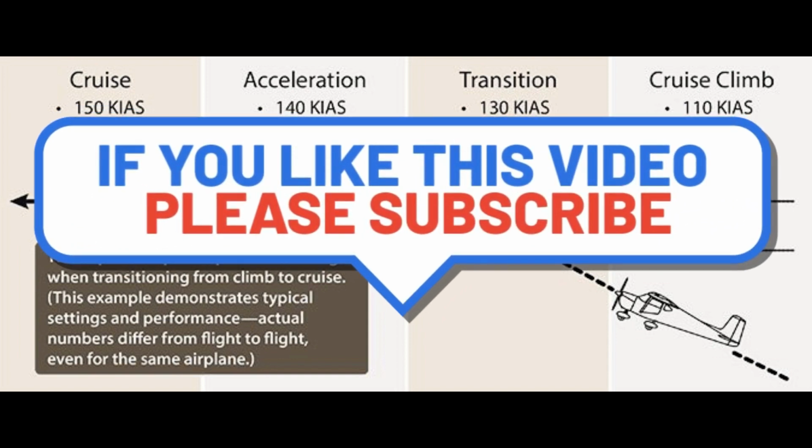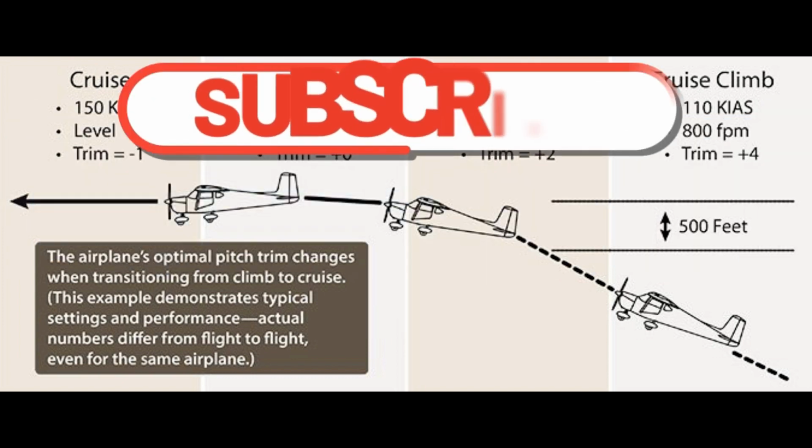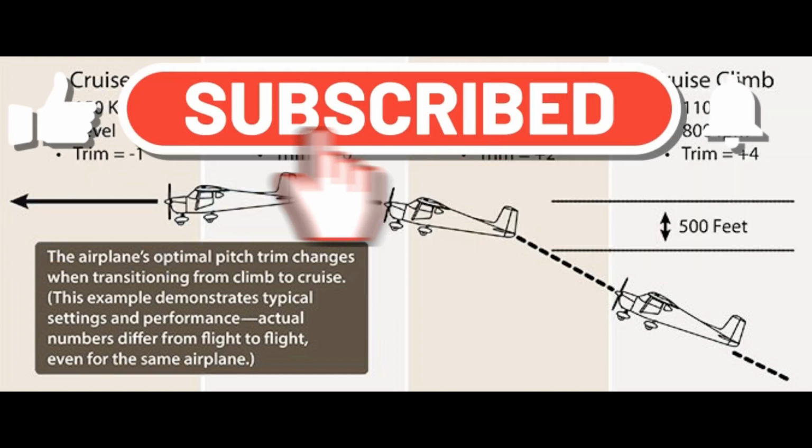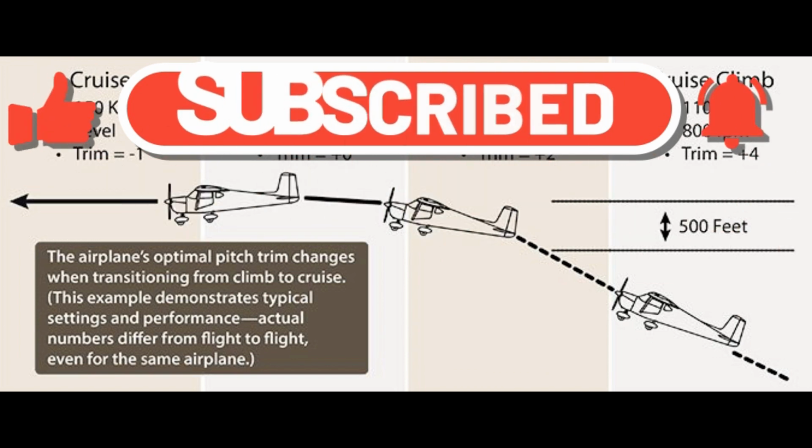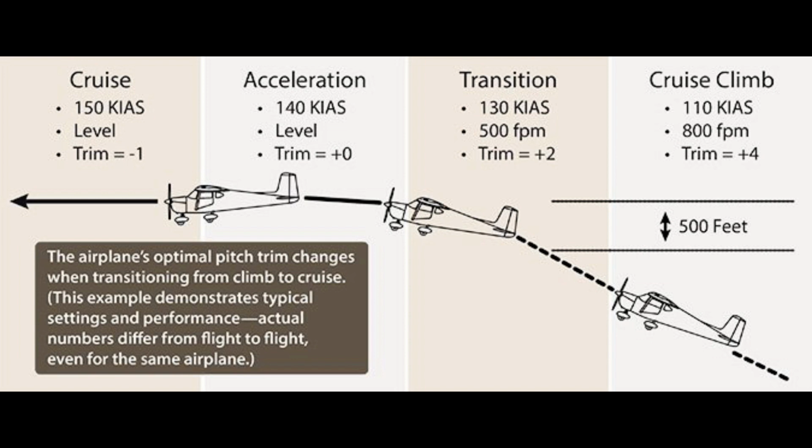6. Determine and record maximum climb vertical speeds and power settings for temperatures and altitudes. Ensure the values are in agreement with values in the AFM/POH for the conditions. Make note of highest practical pitch attitude values, conditions, and loading. Remember power plant factors, e.g., minimum power plant temperature, bleed air requirements, and airframe limitations, e.g., VA in setting power.